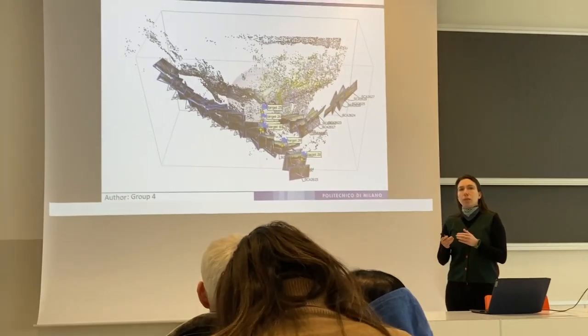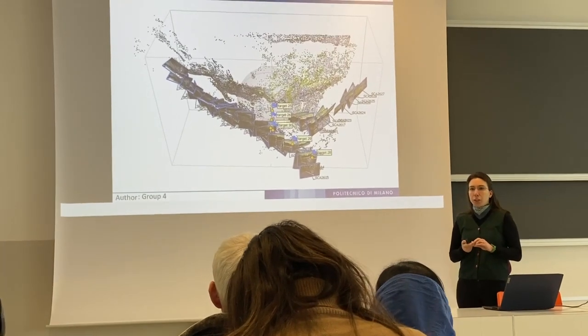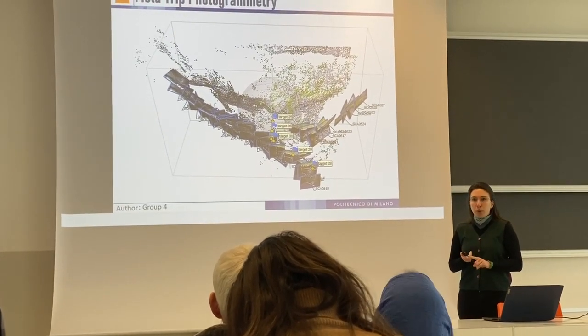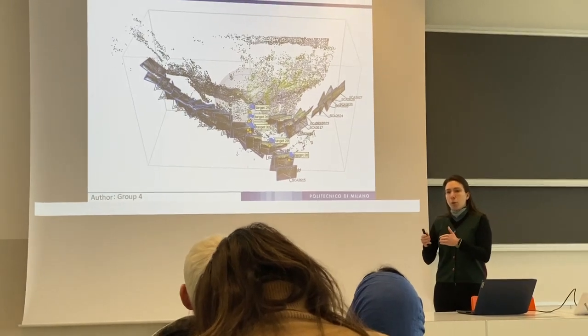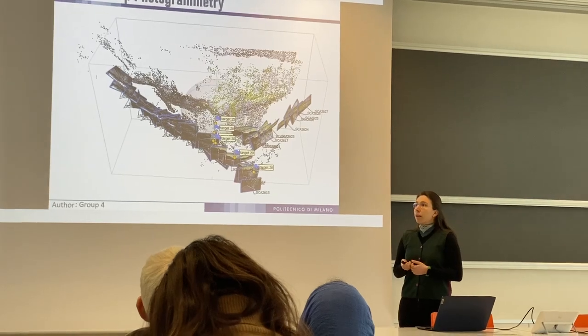In that way we decrease the error. The most important part of using Metashape is to produce the point cloud, because we use this point cloud in CloudCompare to find the dip direction values.